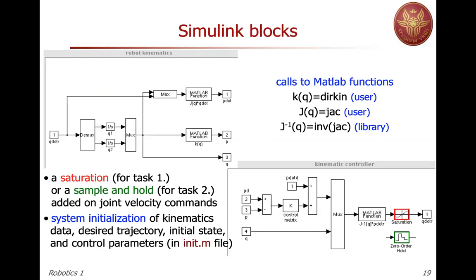And now you see there are two blocks added in the kinematic controller to make things more realistic. One is the saturation. So my velocity command, whatever it is, cannot exceed some limits. This tries to keep into account the presence of limitation in the low-level direct control and also in the actuators. And another block which may be substituted or put in series to the previous one is a zero-order hold element,